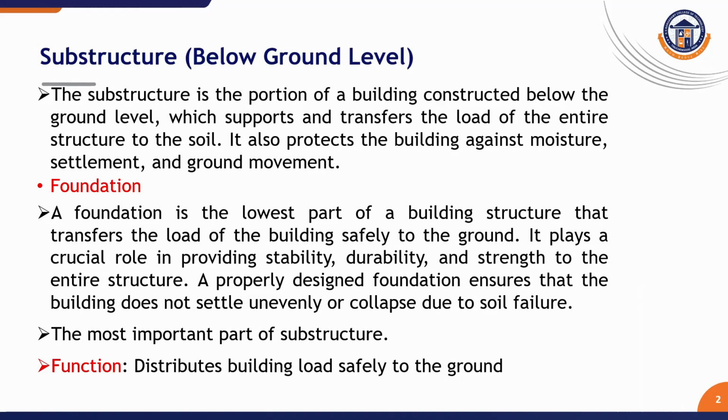The substructure is the portion of a building constructed below the ground level which supports and transfers the load of the entire structure to the soil. And foundation, a foundation is the lowest part of a building structure that transfers the loads of the building safely to the ground. A foundation means all the loads are transferred below the ground level. That is called as foundation, the most important part of substructure. Functions of substructure is distributes building load safely to the ground.